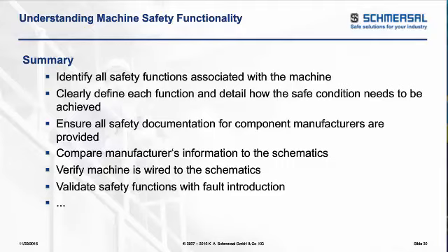You need to work concurrently with your controls engineers, your mechanical engineers. How are we achieving the safe state? Are we in agreement with this, that this is being done per the level of the risk analysis? The engineers need to help educate EHS on the things that are actually causing the hazards, because we can walk up to a machine, open up a door, and look and say, that's going to take my finger off.